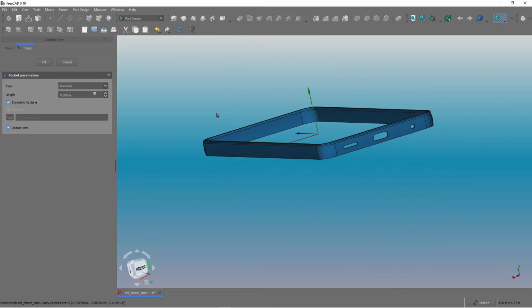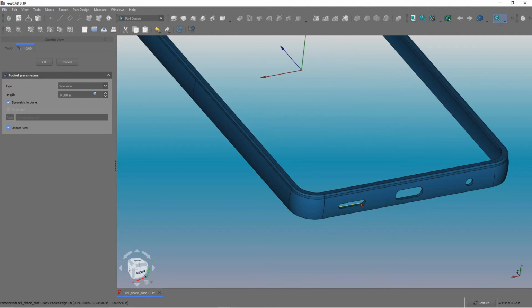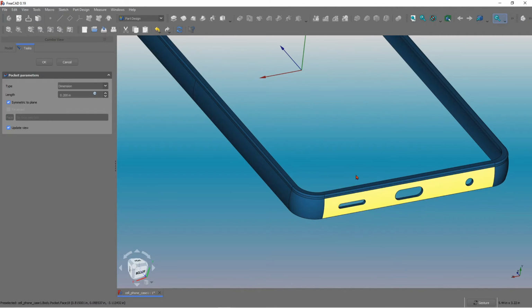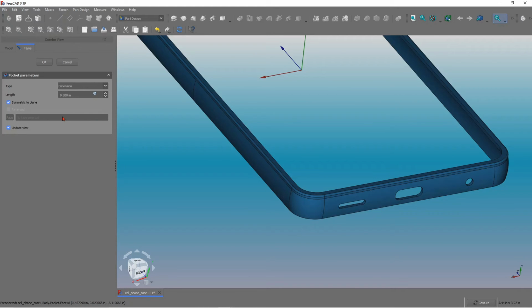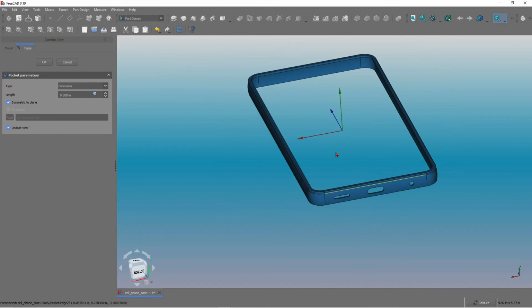Yeah, so what happens is, my sketch was not exactly on this face, it was somewhere in between the bodies of this, between the wall surfaces. It only cut one side and it did not cut the other side. So when I did the symmetry, it cut both sides, and that was the reason. So that fixed that problem.